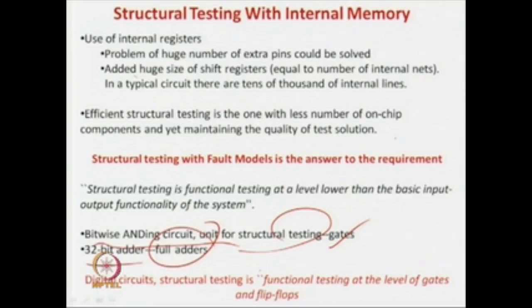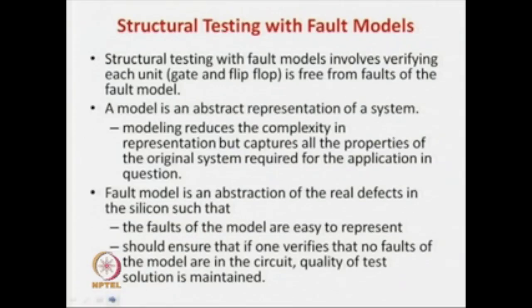So in a digital circuit, structural testing is basically functional testing at the unit of gates and flip flops. Flip flops and gates are considered units in the general structural testing terminology. The full adder was only used as an example, and you should not think of it as general terminology. It was only to illustrate what structural testing and functional testing are.